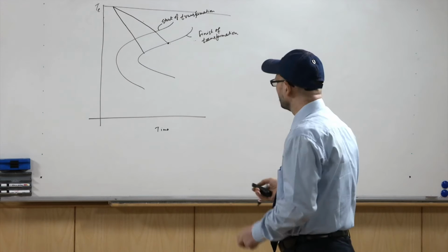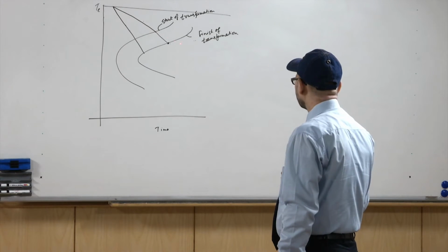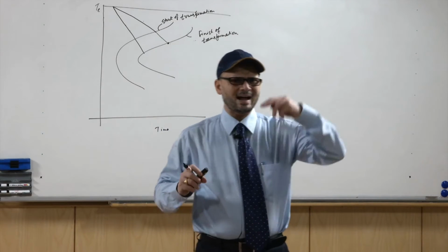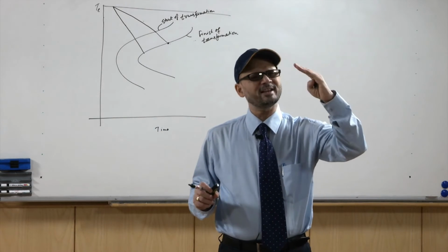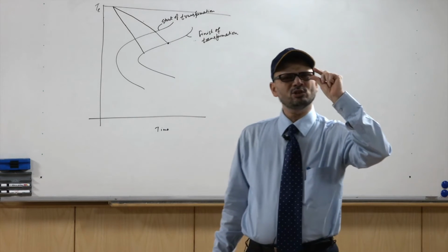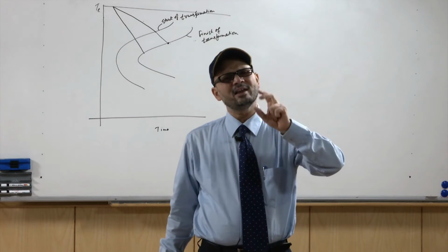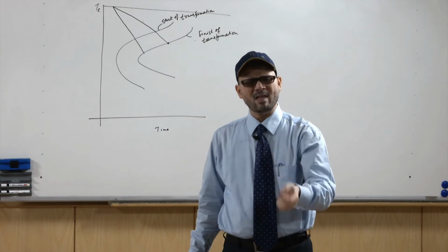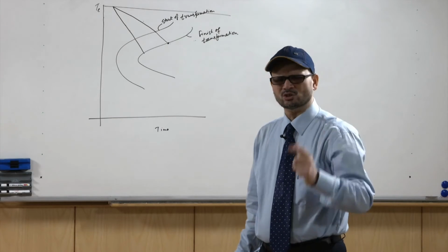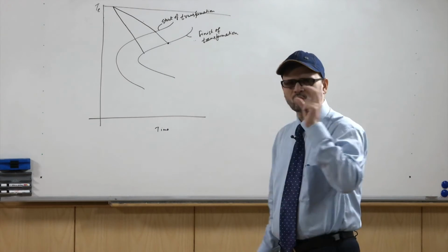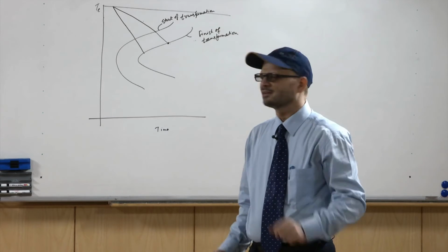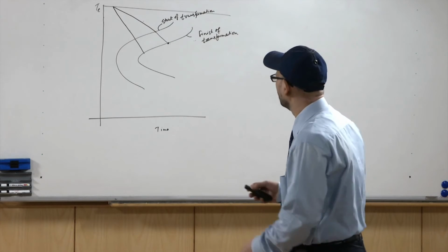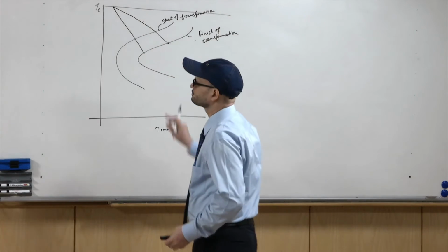In the case of a slow cooling rate, because of the higher temperature it is experiencing for a larger time, nucleation is not predominant, in fact growth becomes predominant, and the growth process leads to formation of the coarse kind of pearlite structure. That is why you get this coarse pearlitic structure when your cooling rate is like this.